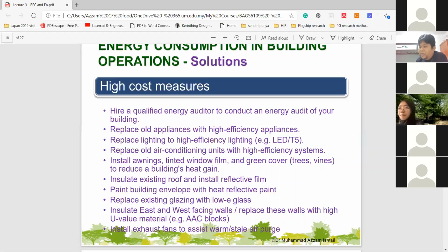And then at the same time, usually building owners don't wash or clean up their cooling towers. They don't go and clean up their aircon plants. They don't go and clean up the aircon water tank. All these equipment have to be cleaned up and maintained regularly, to maintain not just the efficiency of the system, but also the health and well-being of the occupants.